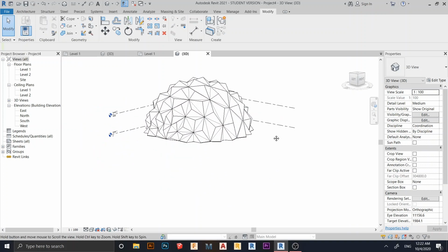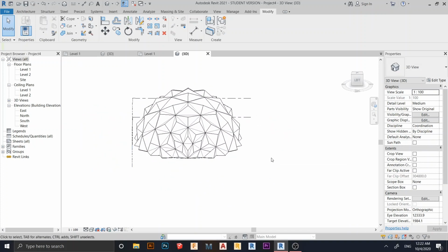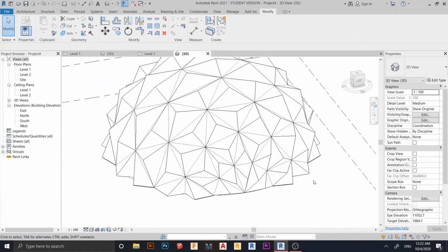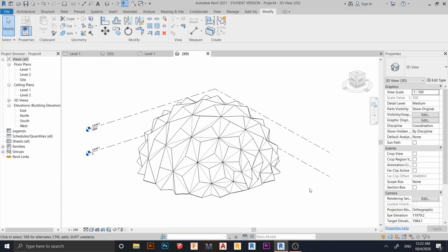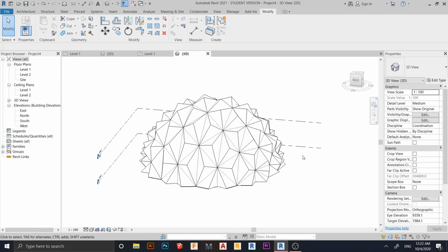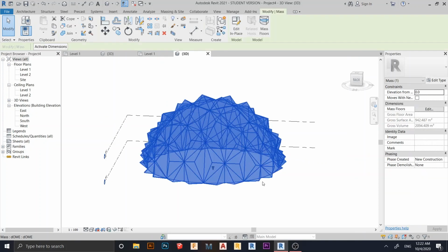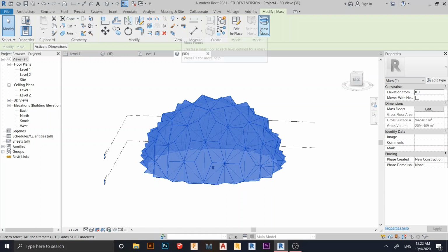As you can see now, everything is quite fine. It looks parametric, it looks a lot better, and of course you can add a floor plan as well because we use our massing inside. You can add another floor here and floor here as well. Let me give you a concept. You just select here, then you can select the mass floor here as well. For create floor, the floor will follow this one.